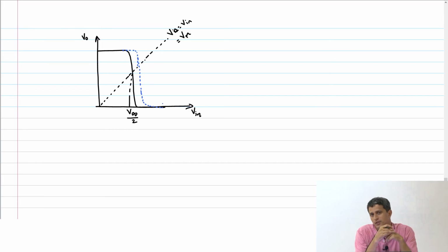No, why? That's what I'm asking. So for the same V in, you are saying that the PMOS now has a higher current, right? So how will V out adjust itself to accommodate this higher current? If my width goes up, I'm able to accommodate more current in the PMOS transistor just because of the width.